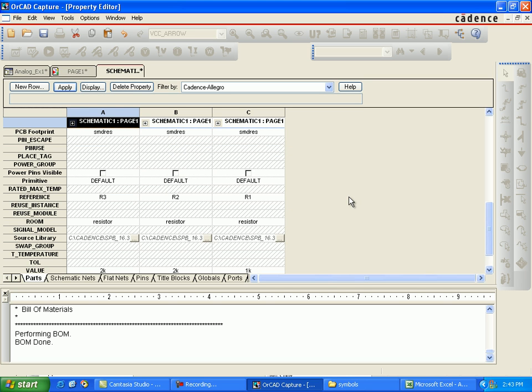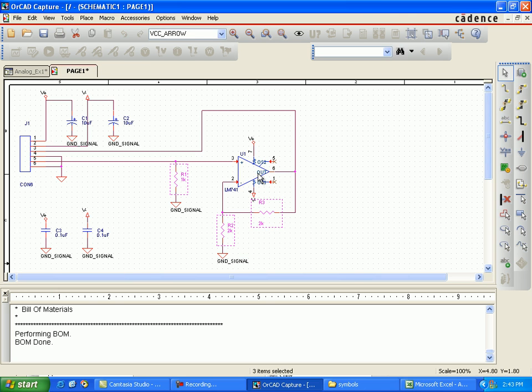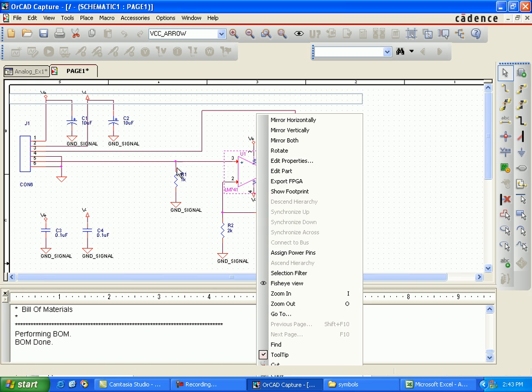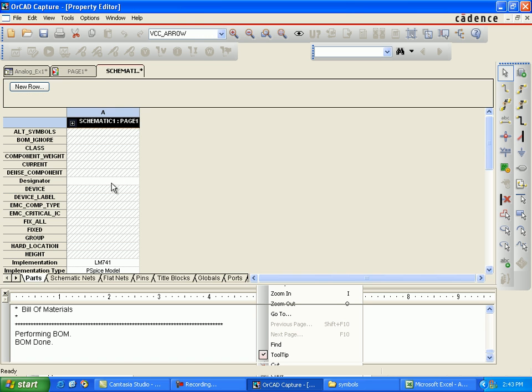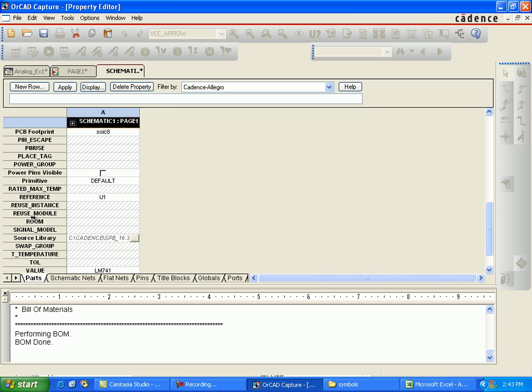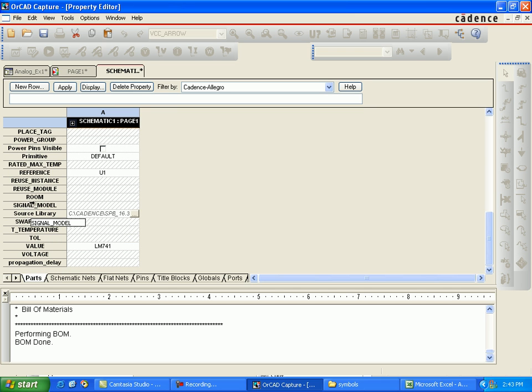All the resistors. This is very important because in a complex PCB, this is a small PCB, but in a complex PCB you want to make all the components in one room. It just helps you in analysis: if you want to change one component, you can see what's going on with the other components. That helps a lot. Also in making the silk screens, whatever you want to do on the PCB, if you have rooms, it helps you.